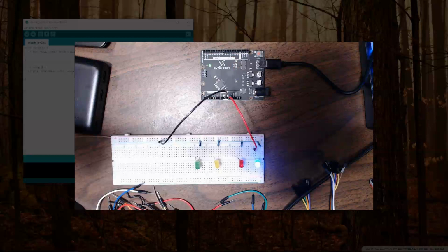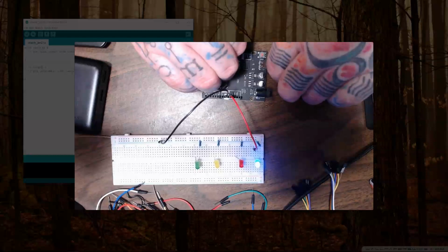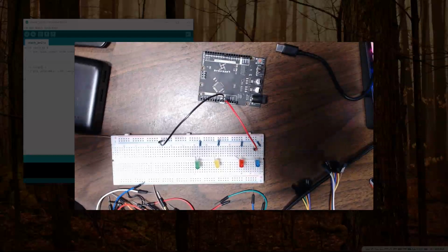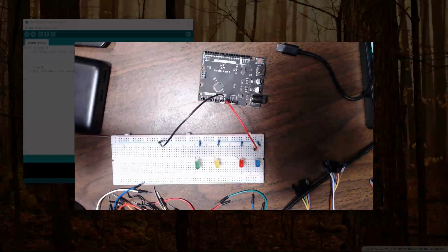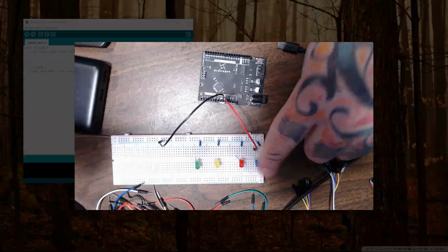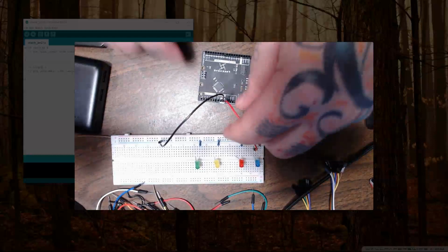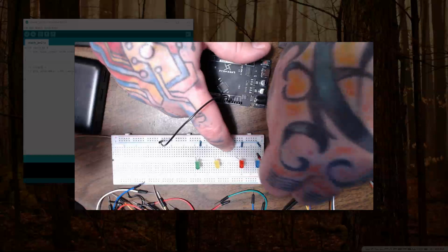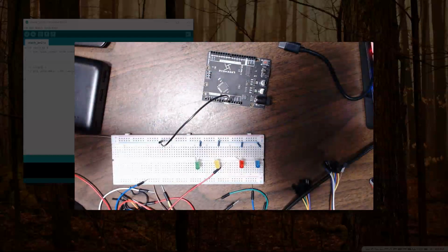So next thing, I want to rewire this. Again, normal procedure is disconnect everything from your power. So unplug it from there. And now the ground is always going to go to GND for the negative terminal. But now to control the power from the pin that we are actually working on, the LED, we are going to use one of the GPIO pins, which will be used to indicate whether we have power going to it or not.